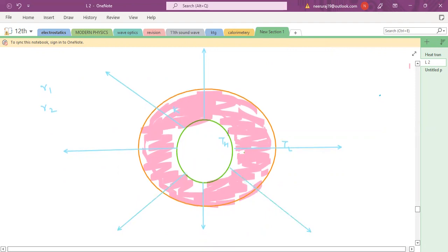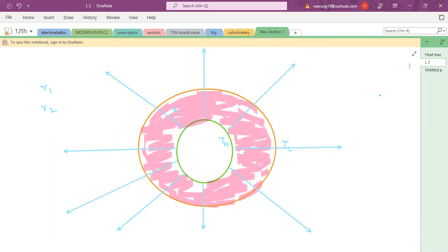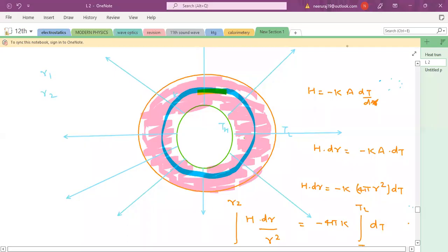Almost, this theory is like the wavefront, because in wave theory also there is energy flow, and here it is current flow. So in terms of wavefront, here the wavefront will be spherical. In the previous problem, the wavefront was like a cylinder. This question is also a three-dimensional current flow. Here also the area of cross section is continuously increasing as I go from R1 to R2.